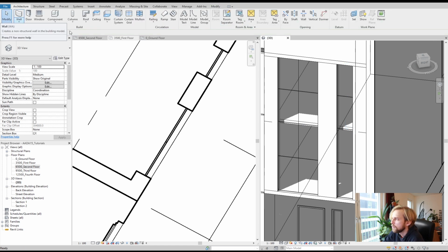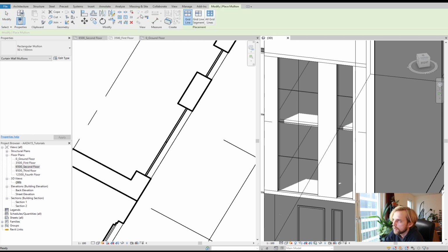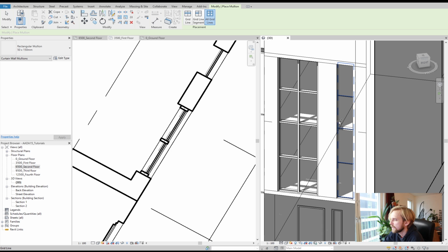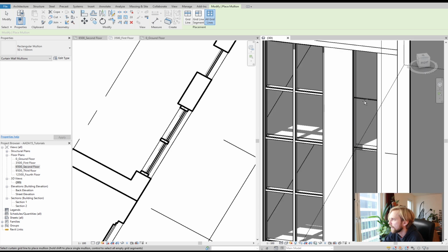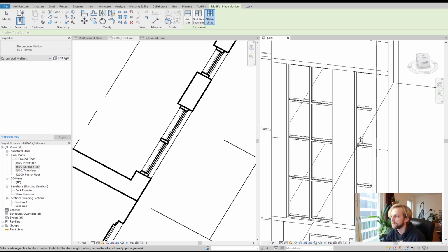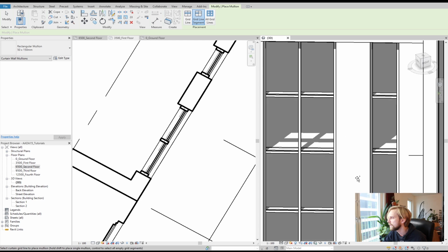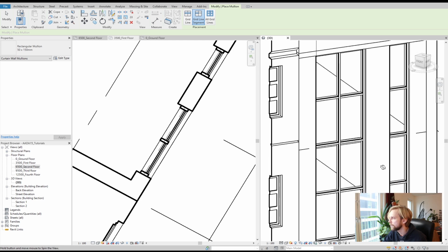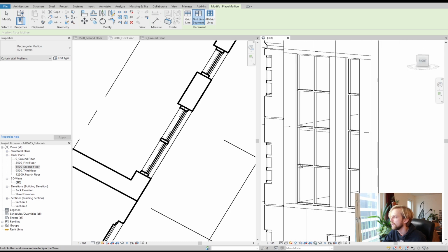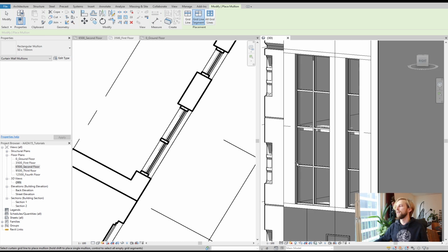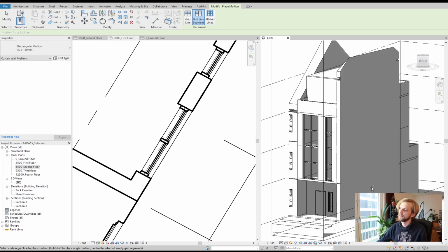And then I'll go to Modify tab, I'll click on Mullion and do the same thing. You know, rectangular mullion, all grid lines. I'll choose the button that says all grid lines and say that all of these need rectangular mullions, right? And these also need rectangular mullions. So now all of this is kind of done, it's kind of set up, right? We have our facade done.